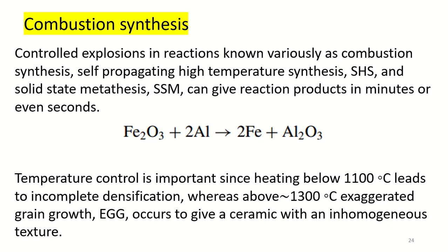The SHS method, self-propagating high temperature synthesis, was pioneered by Russian scientists. Starting materials are chosen that react together exothermically. Consequently, once a reaction is initiated, enough heat is generated for high temperatures to be attained and complete reaction occurs rapidly.